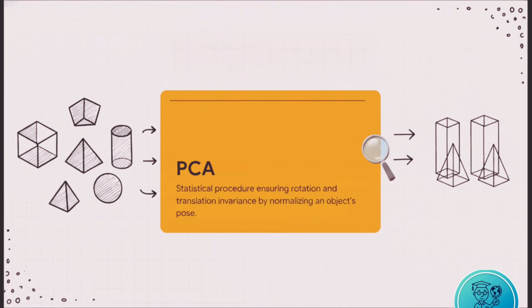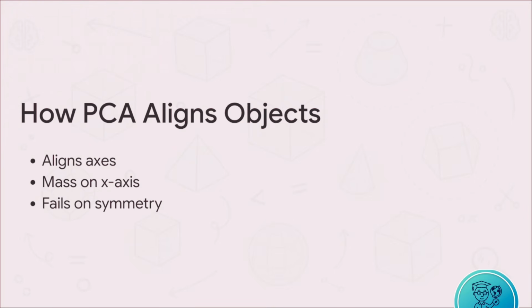It acts as this absolute mandatory pre-processing step. By running PCA on the triangle mesh before we ever calculate the descriptor, researchers ensured translation and rotation invariance. It essentially guarantees that similar objects are going to have similar orientations, setting us up for an accurate match. So the crucial point is how this auto-alignment actually goes down in 3D space.